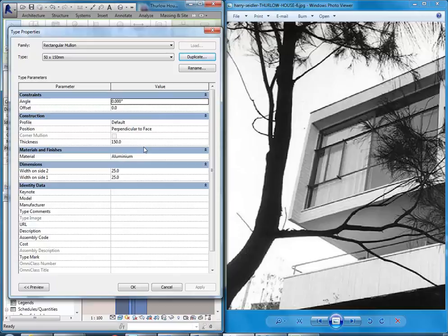And it's doing the same thing. Okay, so I'll have a look at that. There must be a different type of mullion in there somewhere. But yeah, so just try going to Edit Type now, and then see. Yeah, so they must be type driven, I think. So you'll need to have a look at your wall properties. It's that good curtain wall. Yeah, I'll have a look at that in a sec. Yeah, so it's to do with the wall.